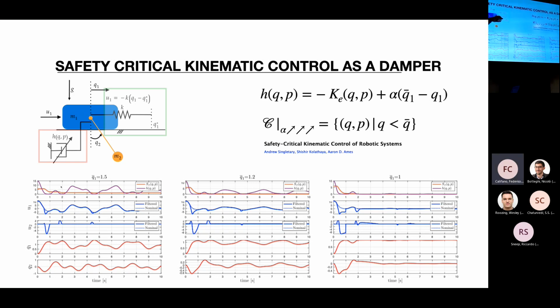And you see that the spring and this variable damper, which is to all effects a variable damper, and the fact that this is a variable damper is proven in the theorem, is proven in the paper, because I proved that the system remains passive, which means basically that this acts as a damper in this circumstance, which is not an obvious thing, no? Because the control effect from this comes from an optimization. It's not an obvious thing, but the spring and the CBF effect interact in such a way that they achieve regulation basically to 1, even if there is no dissipation term, there is no damping action.